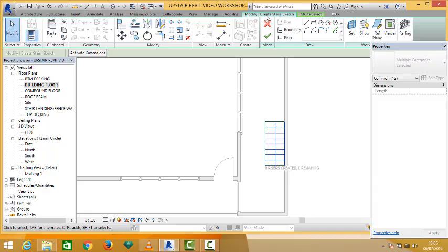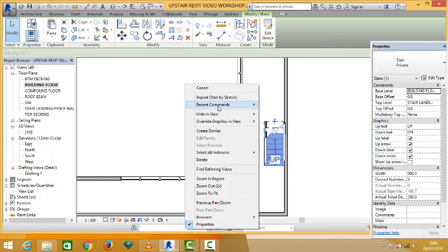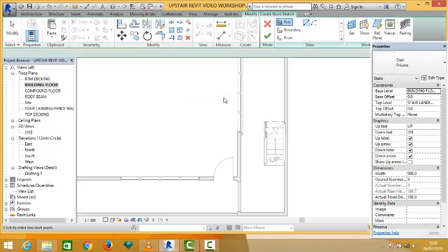Okay, we'll come back to our modify / create stairs check, and we say okay. You check the green good mark to okay what you have been sketching. So now very quickly, I can right click, and in my resulting context menu I will say repeat stair by sketch. Okay, I pick on my line. All right, all my stair parameters are okay. Now my desired number of stair here will be longer than the one I had here before. It should be in the vicinity of 13, 14, but now I have 9.